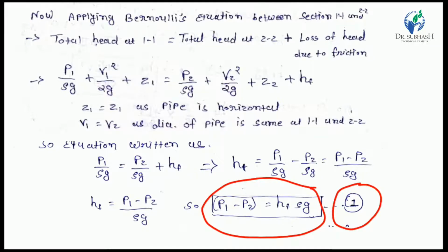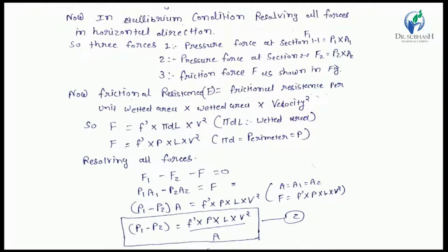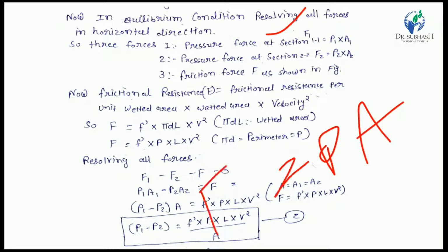Now, in an equilibrium condition, resolving all forces in the horizontal direction, we have three forces: pressure force at section 1, pressure force at section 2, and frictional force. We know that pressure force is pressure into area.